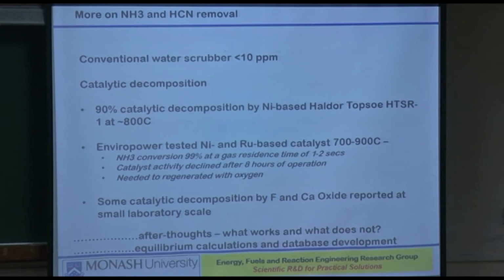So, the important thing in all of this is first and foremost, find out through equilibrium calculations what is the highest level these gases will exist when you are subjecting them to processing at a particular temperature. That is the highest level that you can work at. To bring it below that will be very, very difficult. You have to have catalytic loss. That's what the catalyst will do. But the thermodynamics says the limit.